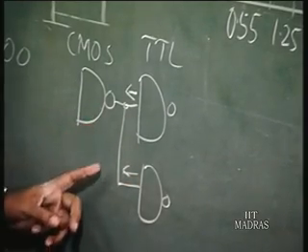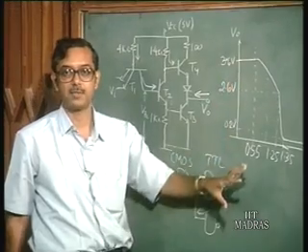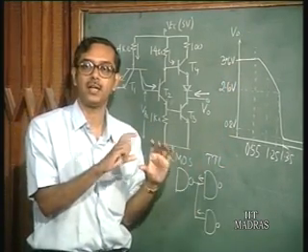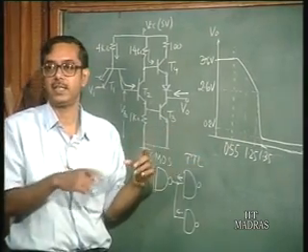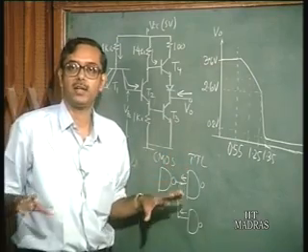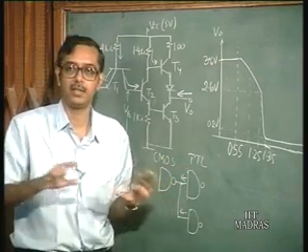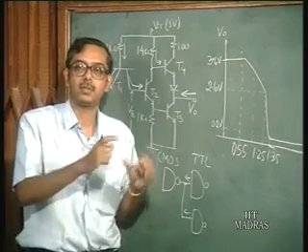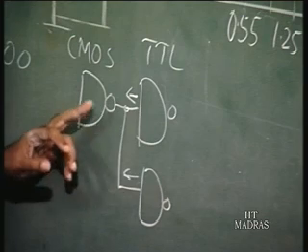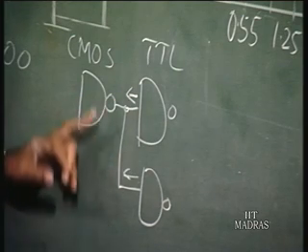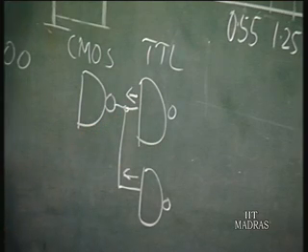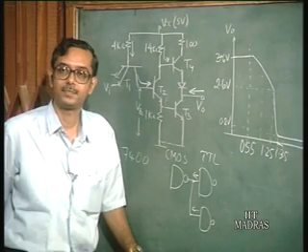This gives you an idea of why this type of specification is very important when you are connecting logic circuits using chips of different logic families. If you buy TTL, with one complete logic family, they may specify on the spec sheet a maximum fan out of 10, and you are very sure. But when you have to connect different logic families, you must be very careful. You must look at the specification sheet, the currents, and only then connect, otherwise you may run into problems. Clear?